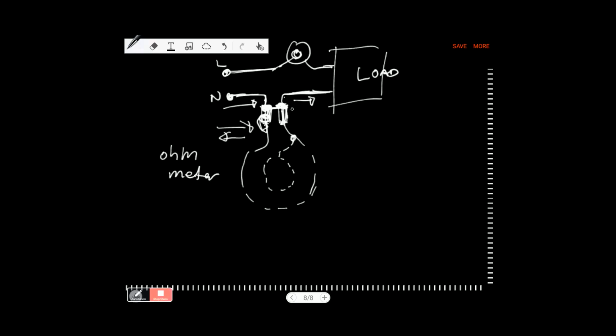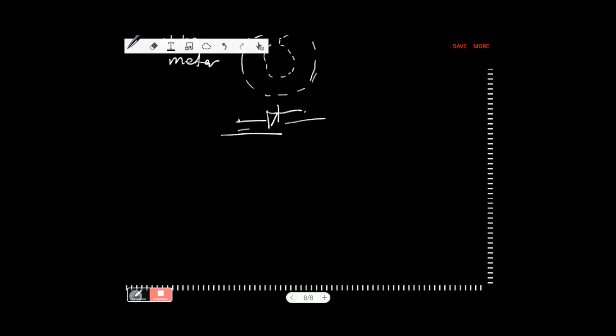Connecting it as a diode, it should always be in series. Just like an electronic diode, the flow should go through the diode. It's not that the diode should be connected across, but the flow goes through the diode. That's how we connect a diode if you want to block one way and allow the other way. Okay?